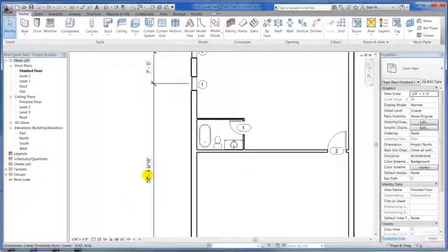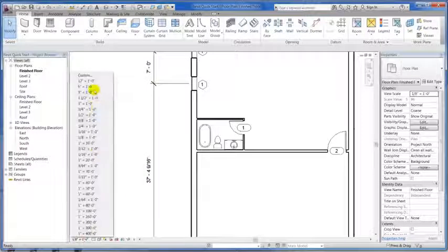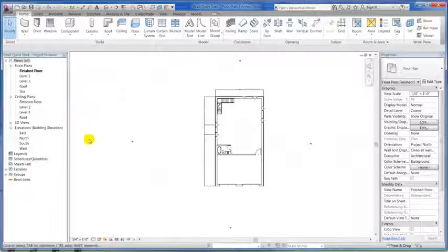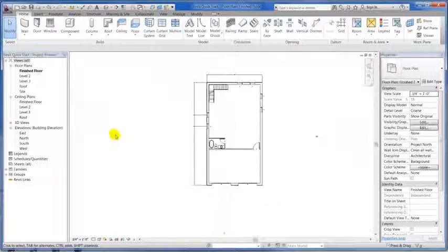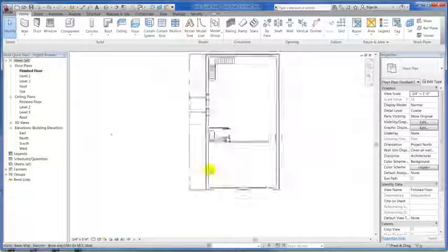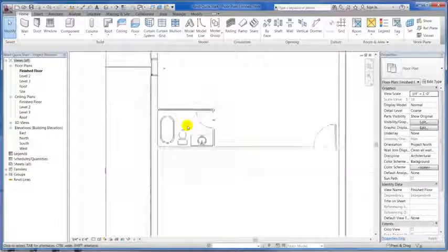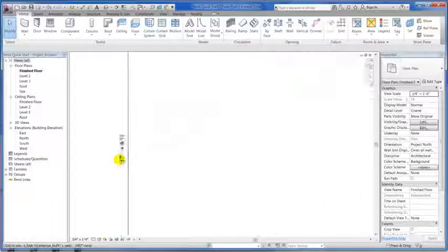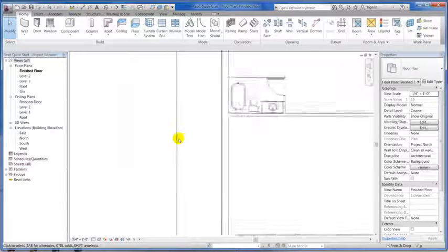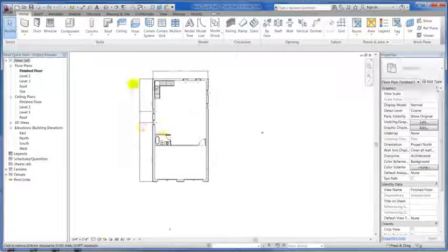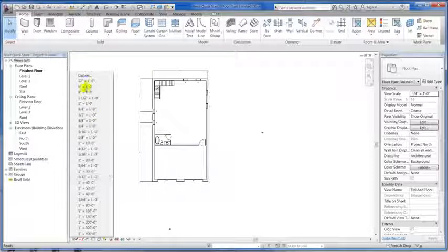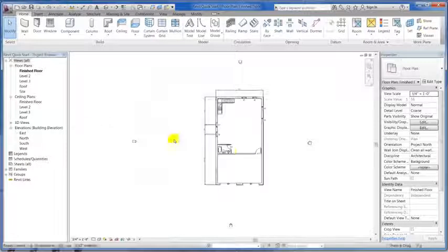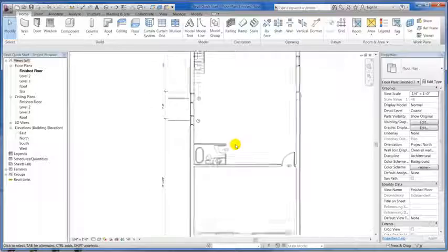If you look at the dimensions, everything's annotative. So this is how I change my scale. If I want to change it from 1/8 to 3/4, let's say, see how tiny the callouts for the elevations, the tags, and the dimensions got? Very tiny. You can see overall how tiny they are. If I go back to 1/4 inch, you can see they're a little bit bigger.